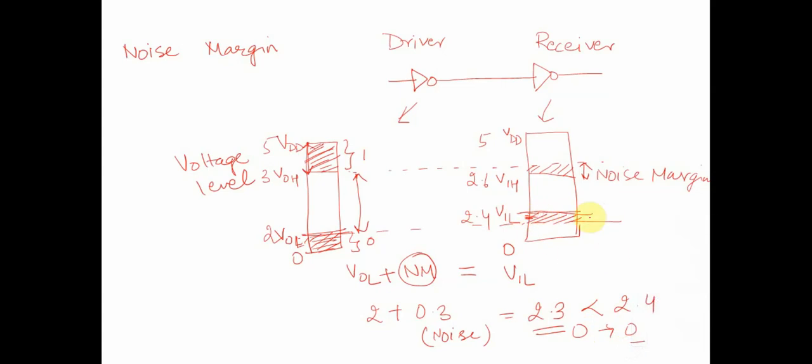Whereas in case we don't have this noise margin, or let's assume this noise margin was less, say 0.2, and we send this and the signal picks up a noise of 0.3 voltage levels, the signal value over here is 2.3, whereas my upper limit of voltage was 2.2. Now it will fall into this unknown region. Basically we cannot determine it, so this is called the indeterminate region. Once we fall into this particular region, the value is non-deterministic, it could be anyone.